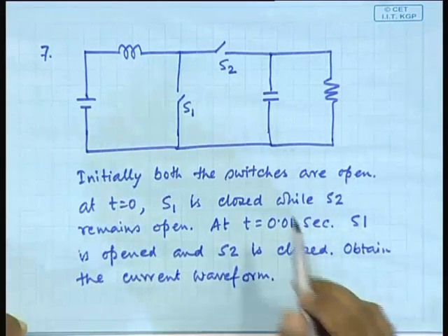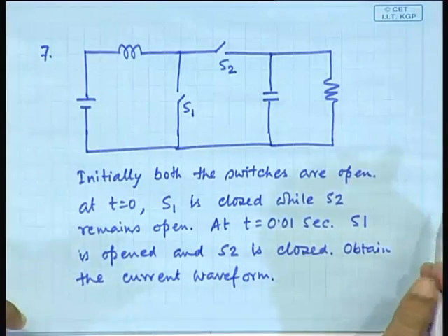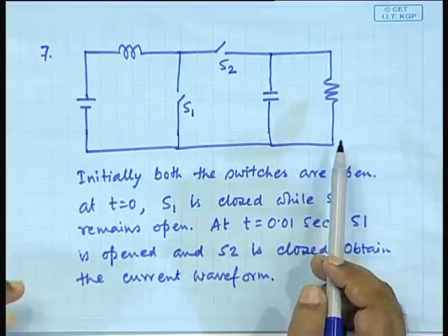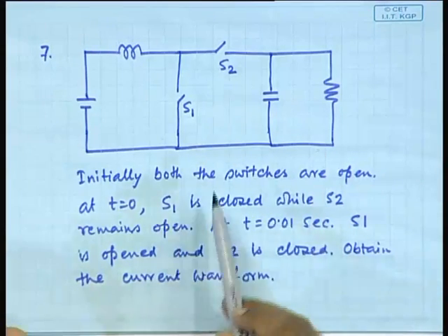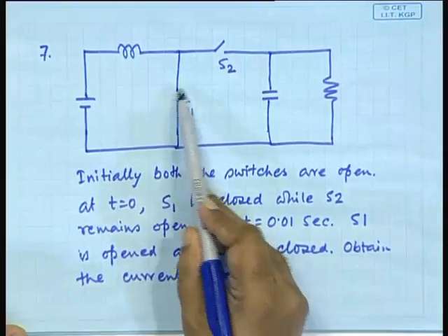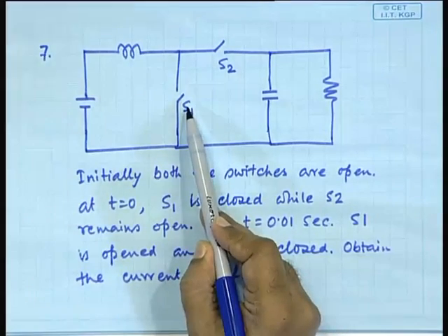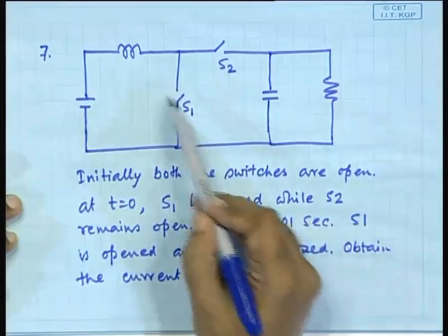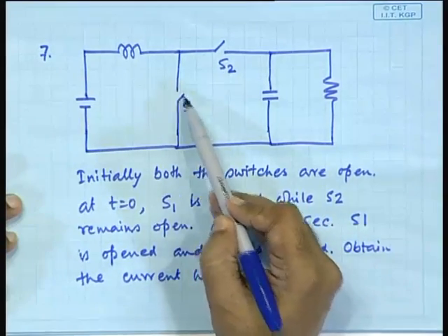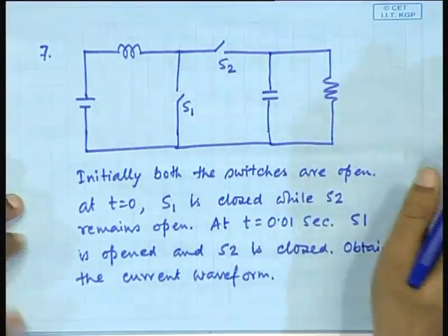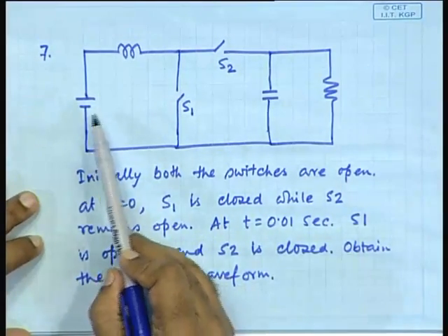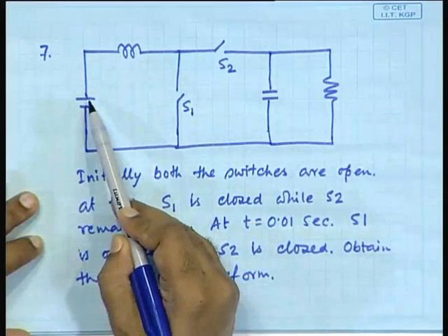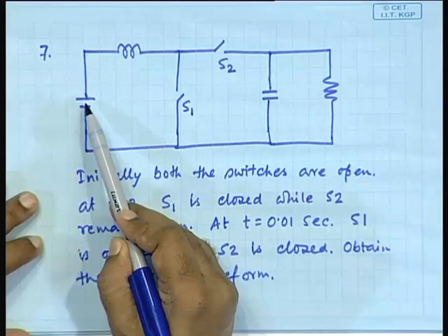Those who have read a bit of power electronics would immediately realize that this is nothing but the boost converter. So, when we talk about S1 being open, normally this is realized by means of an independent switch, a MOSFET in general, and this is a diode. Whenever there is a switching on and off, this operates complementarily. So, initially what is the circuit? When S1 is closed, it is only this. What will be the waveform then?